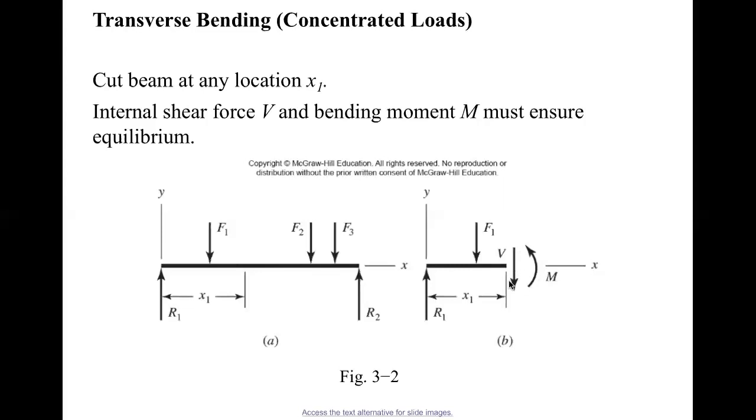Also the shear could be different. So this is a very important skill. You need to know how to use the FBD, the free body diagram, to determine and then apply statics to find the internal shear force and also the bending moments.